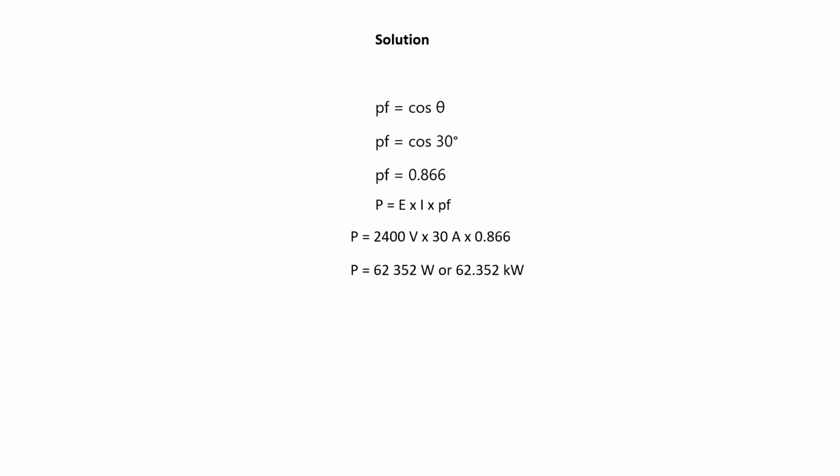Doing so provides a true power of 62,352 watts, or 62.352 kilowatts. The same circuit at unity power factor would be 72,000 watts, or 72 kilowatts.